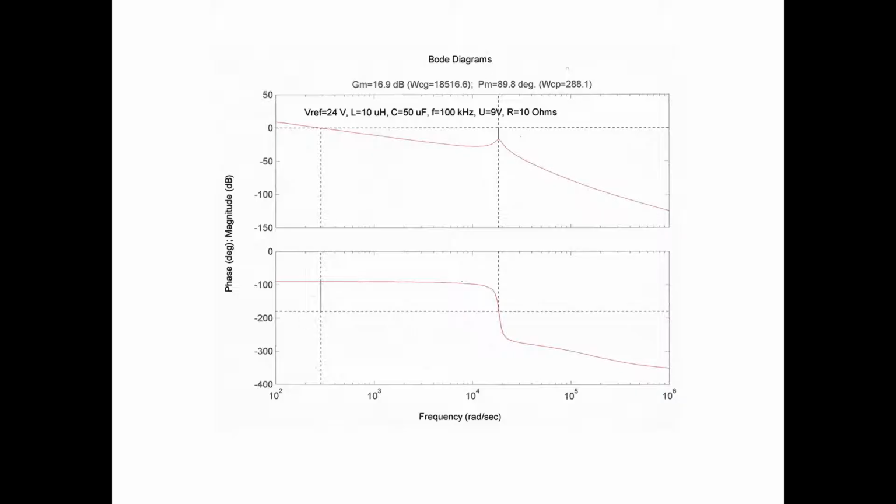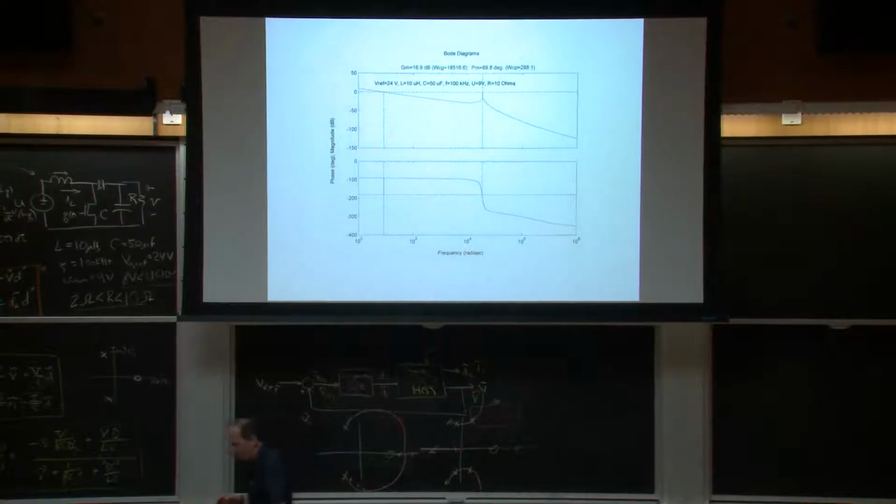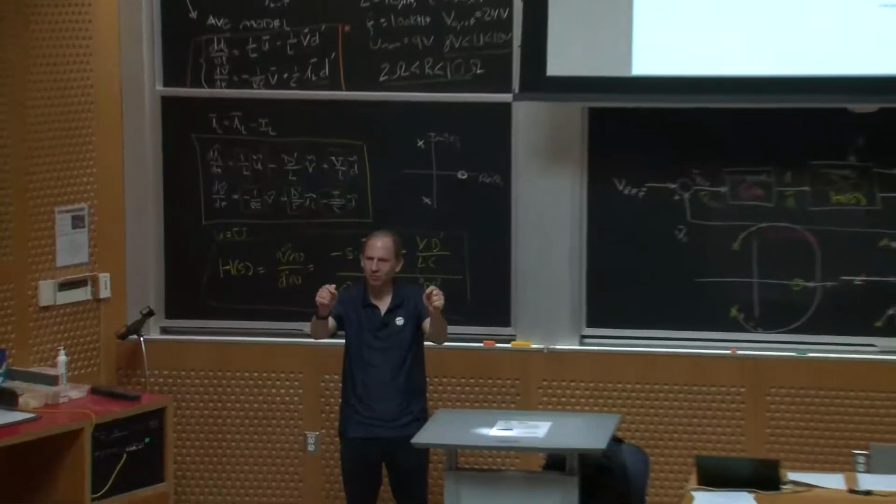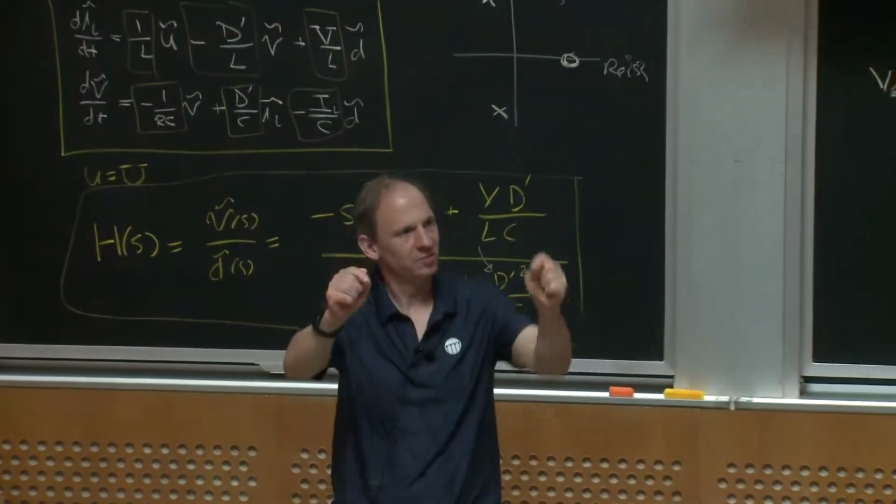And then you have to ask the question, is that tolerable? And maybe I don't care about 30 millivolts of ripple at 20 kilohertz because there's some lightly damped pole pair, right? I could live with that. But there's other applications where they tell you, oh, by the way, you've got to have your output voltage rock solid, and some lightly damped pole pair that's going to get excited by noise and just wobble around is probably not acceptable. So in addition to making your control loops stable, I would argue you've got to think about how precisely it has to track the output voltage? How much will it wiggle when something happens to it?